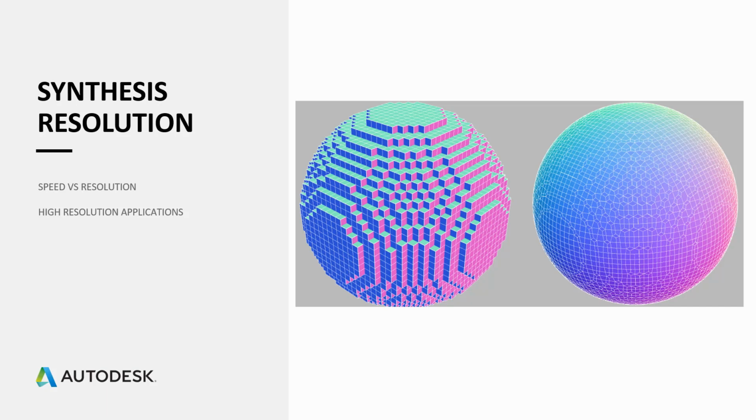So if you move the slider all the way to the left, you'll get a faster solution because it's going to use larger voxels. It's going to break down your design space into larger chunks. So there's less data and less math that has to occur, less data is taken into account in the generative solve process. You slide that thing all the way to the right, and the amount of data goes up a lot, and the speed goes down a little bit, and the total time to solution is going to go up.